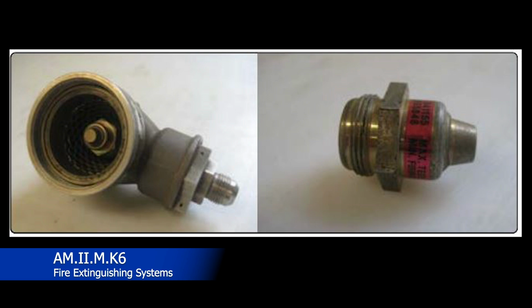Now, two types of cartridge disc release techniques are used. Standard release type uses a slug driven by an explosive energy to rupture a segmented closure disc. For high temperature or hermetically sealed units, a direct explosive impact type cartridge is used that applies fragmentation impact to rupture a pre-stressed corrosion resistant steel diaphragm.